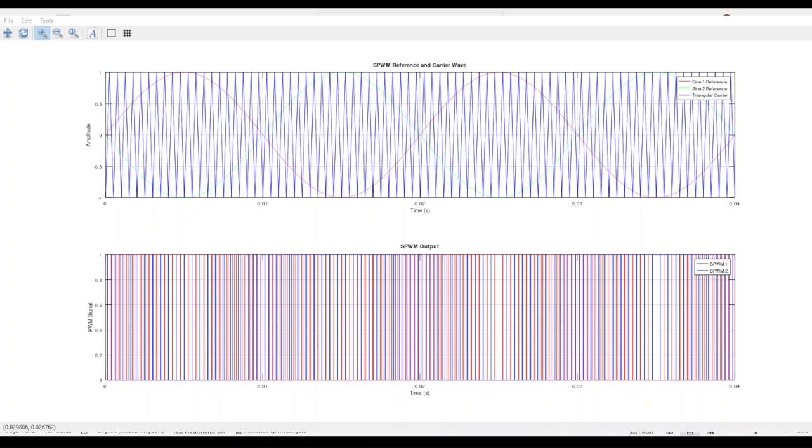All right, now to jump over to explaining how to derive the duty cycle for each point. Before I do that, it's important to explain what's going on here. To achieve this, we have to constantly change the duty cycle. But using a microcontroller and coding firmware for it, you might not want to use a comparator. So you want to load a particular array with duty cycle values, and run those duty cycle values with a specific time delay in between them. And through your inverter, and then after the inverter you get a filter, and then you get a particular sinusoid.